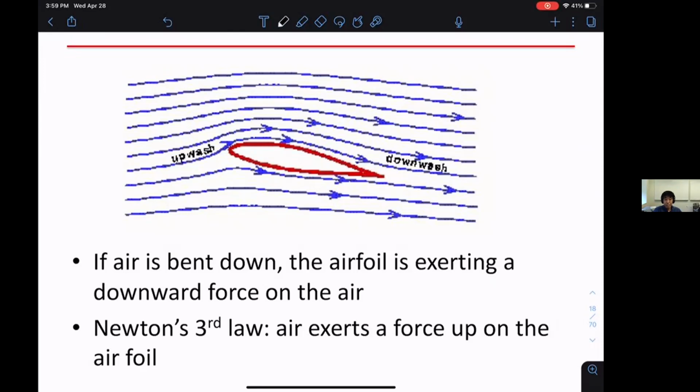Okay, so this is the principle of generating lift. So it makes sense to stop here today. Next class, we'll look at things like how you control how much lift you get. Basically the way to control how much lift you get is how much you tilt the airfoil, or for a wind turbine, what the pitch of the blade is. So next time we'll look at angle of attack and pitch, and understand for a wind turbine how you relate the power you generate to the pitch, right?